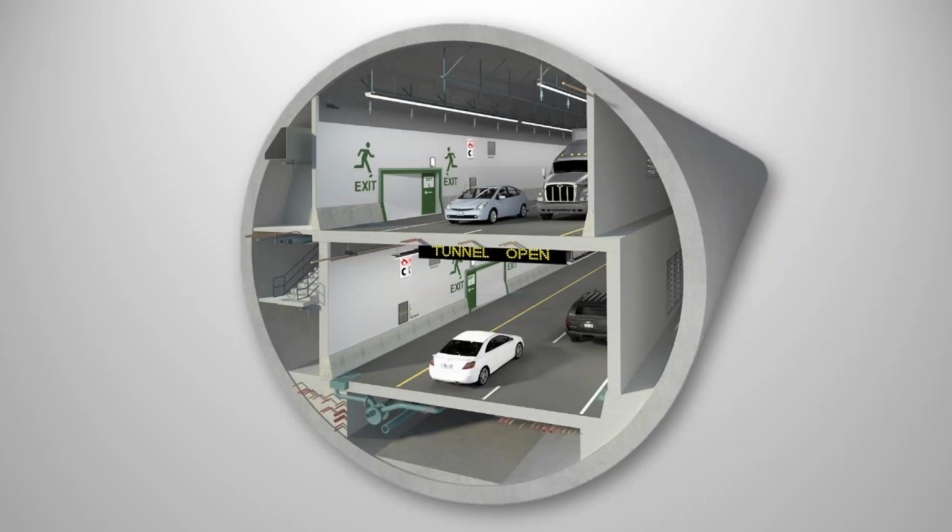So here's an image of the tunnel. At the time when the project started, this was the world's largest tunnel boring machine project, 58-foot diameter, over 17-meter diameter tunnel boring machine was used. And there's roadways top and bottom, both directions. There's passageways for people to exit to safety. They can go out these doors and use this walkway here to evacuate if needed. Utilities in all these corridors, and ventilation is through this plenum here.